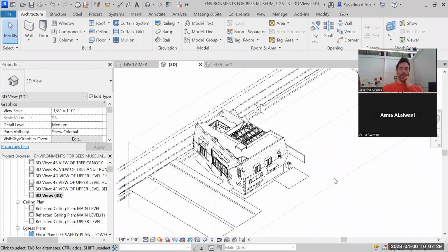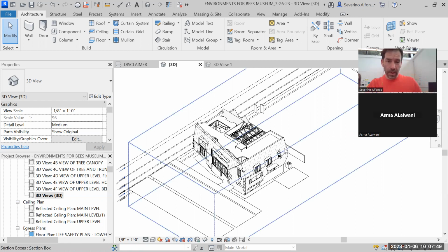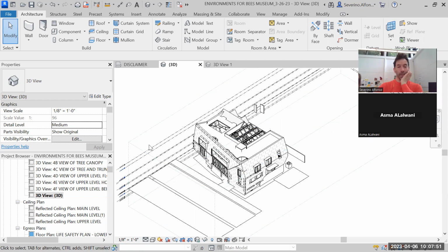The first, most important thing I would recommend is cleaning up your Revit file so you only have the things that you really want to laser cut. Now, because we're dealing with Sarah's project, which is a complex project full of construction elements, I'm just going to do it with this particular view. Everything is going to come from the view. You need to go to a 3D view that has those elements. You don't do it from a plan or a section, you do it from a 3D view, okay?